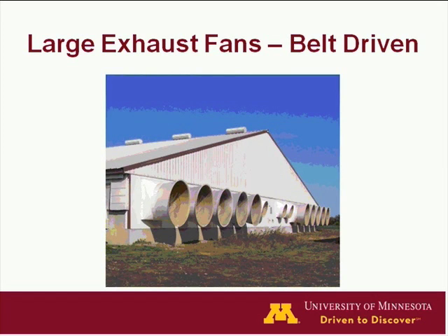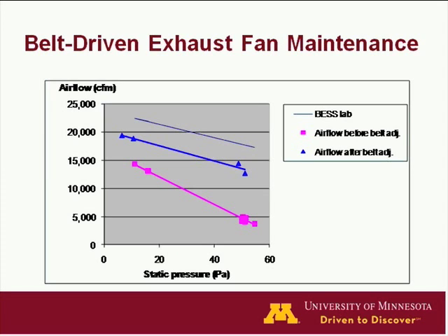Okay, large belt-driven fans are also used a lot in livestock barns. Shown here, they're the primary fan used in tunnel ventilation systems. There are some issues about belt-driven fans that can be a problem, and that's making sure the belt is adjusted or tightened. We did some work quite a number of years ago, a little over 10 years ago, where we were measuring airflow rates from these large fans.